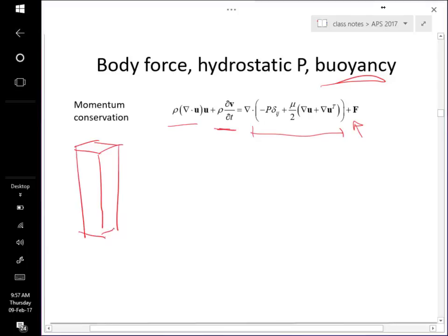So we'll have here a column of fluid that has a free surface there. And let's see, that's the height of the free surface, and that'll be z upwards. And we're really just interested in the vertical effect. So it's just hydrostatic. We want to get the pressure distribution in this, right? So it'll just be a linear pressure distribution, but we want to get it out of here.